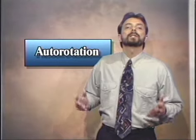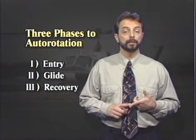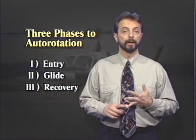One of the most distinctive capabilities of helicopters is their ability to recover from an engine failure in flight by auto-rotating. It's reassuring to know that, if necessary, the rotorcraft can be landed in an area no larger than the diameter of the rotor disc. There are three phases to auto-rotation: the entry phase, the glide phase, and the recovery phase.